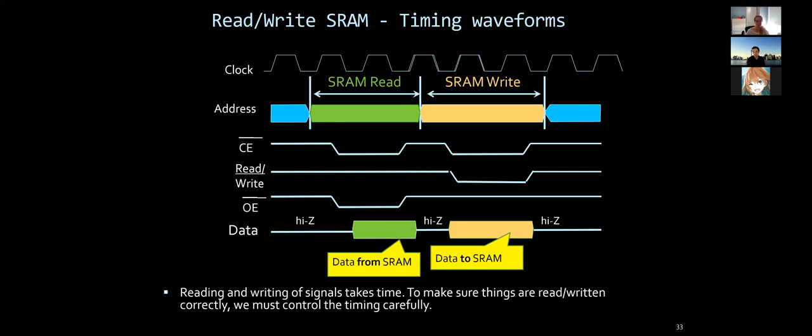So don't get confused, because sometimes people confuse caches and SRAM, because caches are typically built out of SRAM. These are 2 different things. One is a technology. The other one is an abstract data structure that you built to be real using this technology, right? But it has its own design complexity and latencies and all of that.